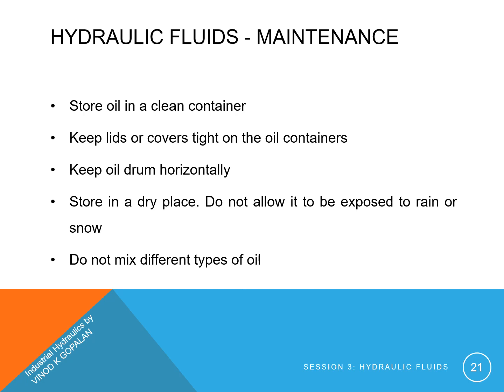Keep oil drum horizontally. I have seen so many people keep the oil drum vertically in their yard or store. But that is wrong. The right way is to keep oil drum horizontally, that is 9 o'clock to 3 o'clock position. Next point is store in a dry place. Do not allow it to be exposed to rain or snow.